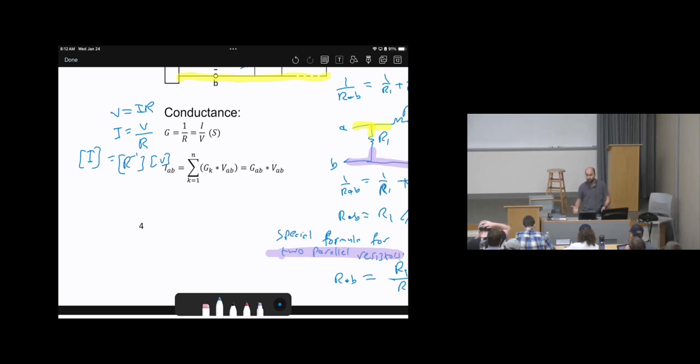Again, the voltage is known. We know what's the voltage, while R is related to the load. So we can know the load, like these classrooms, these machines, this is for the AC unit, so we can predict what's the load. But the thing that we need to do is to calculate the currents. So we will use I equals R inverse times V. Again, we're using inverse because we are dealing with matrices. Then, in order to deal with these matrices, most likely we will use software to do it.